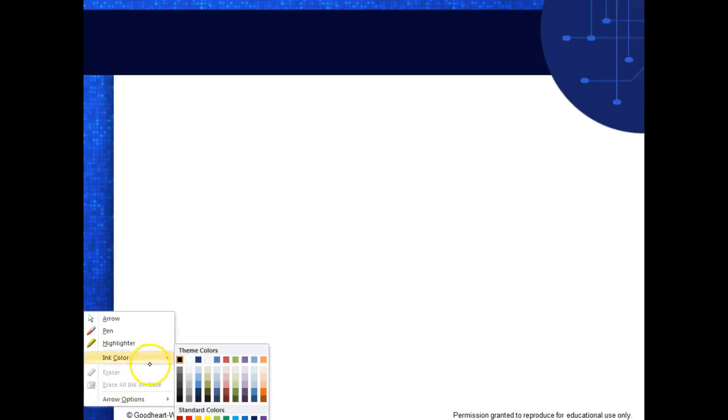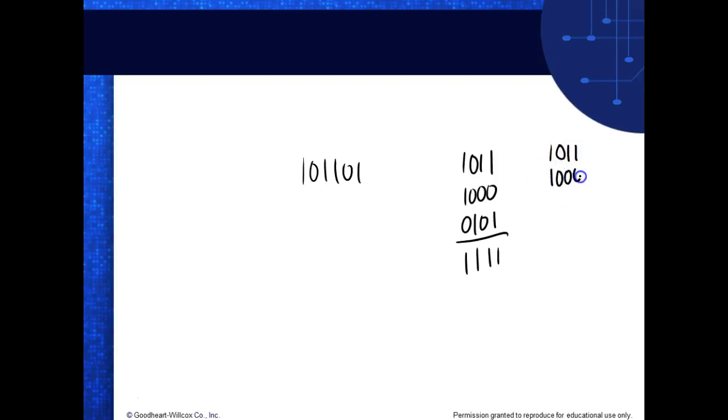So I'm trying to OR it using the commands we're working on now, not contacts. Okay, let's just do forward. Let me do it in 16 bits. Let's say I wanted to OR this with that, and I wanted to OR it with this. Well, if I did that, this would be a 1, this would be a 1, this would be a 1. Right? Okay. Well, how would I do it with OR instructions? Well, I would take these 2 right here, and I would have 1 OR instruction, and then I would OR it with this. And that would give me this, right?